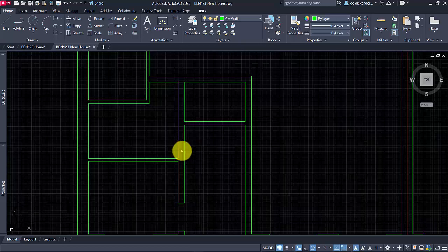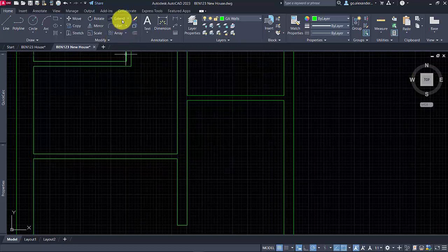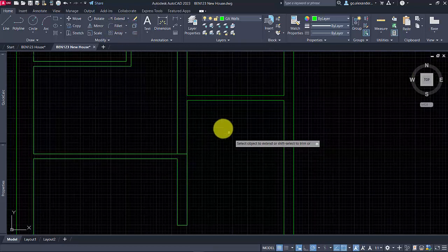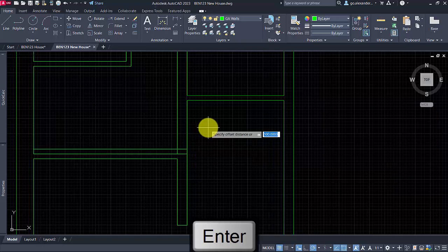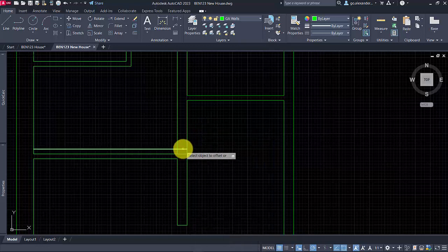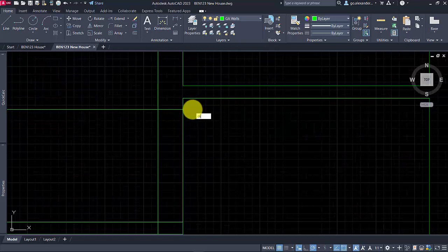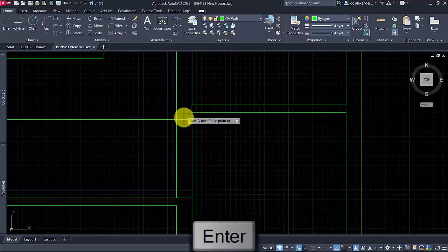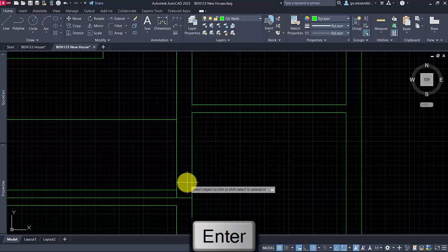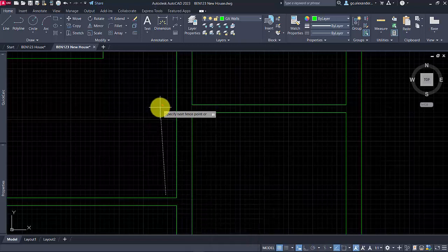And then with the WC here, we can do the same. So let's just extend that line temporarily and then offset by 100. And then again offset by 910. So let's just check this dimension up here, what it is. That's 90 millimeters. That's just about okay. You want to have something close to 100 millimeters either side of the door, just to allow for things to happen around those openings. Try to, oh, what am I doing?